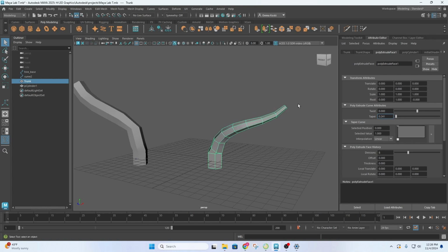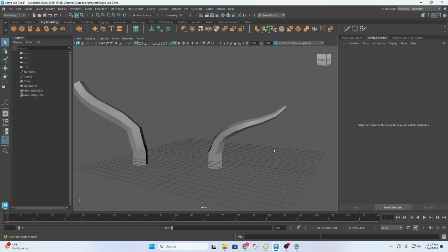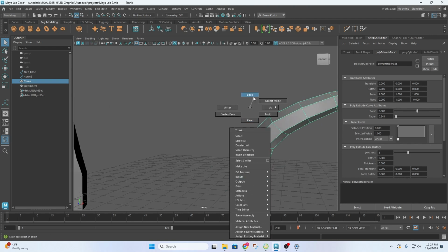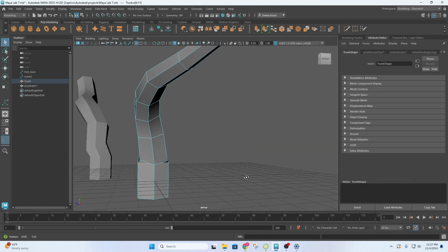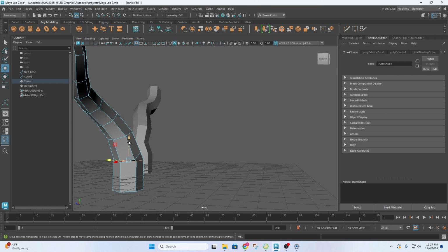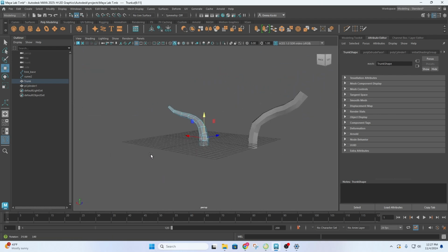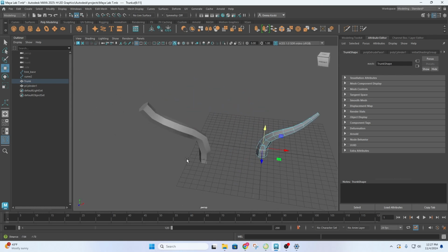You see how that's changing the geometry on my tree trunk? So I'm adding a taper because the end of a tree isn't as fat as the beginning, right? So I'm changing it down so that it fits thickness-wise. It kind of tapers off, okay? And then after you've done that, you can come in, and if you see any weird geometry like this, you can grab that edge loop and kind of adjust it, move it down so it's not overlapping, right? So you should have just tapered your object.